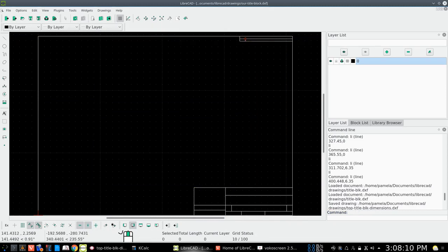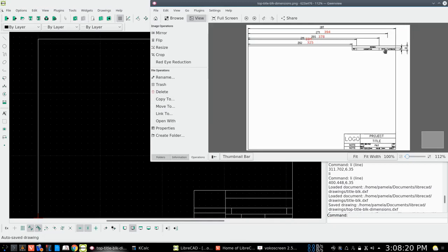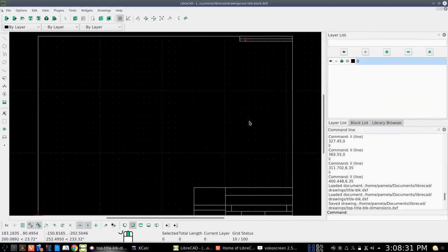The next one is going to be 378 over and 279, which is 8 less than 287. So we're going to be 378 over and 279 to set our first point. Up arrow key, line, up arrow key.